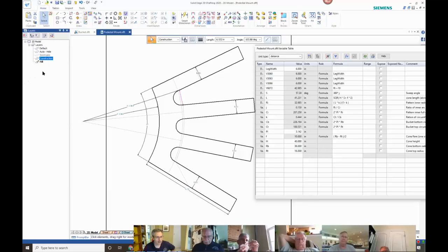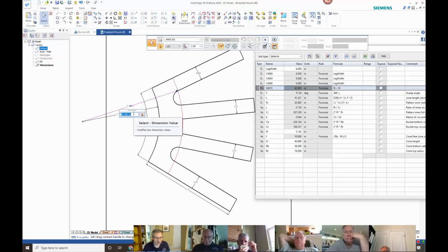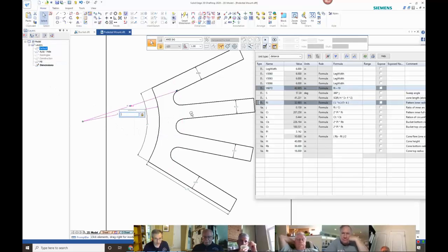Fill. So I'll create a layer for the fill elements. And you can hide and show the elements using this one. So right now, construction is shown, but I want to hide it. So if I click hide, you can see all those gray lines went away. I can create another one for dimensions. And if I don't want to see the dimensions, I can select them. Again, I'm holding down the shift key to select multiple things at one time.